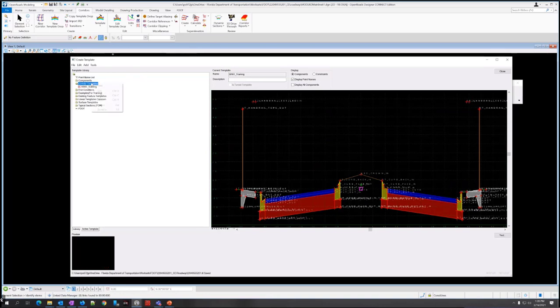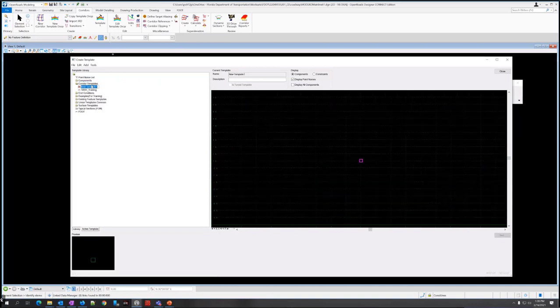So we're going over here to corridor templates. If I right click and do new template, it's going to create a nice blank one for us. And in step 2, it shows you how to rename it. We already did that. So if you notice here, it just goes straight into editing. So you can just type the name. So I'm going to call it RR98 training. And I just hit enter. So double click on that, make sure it's active, or right click and do set active.